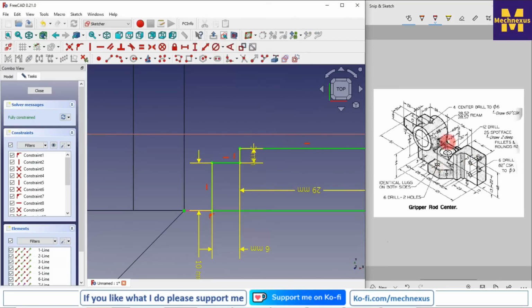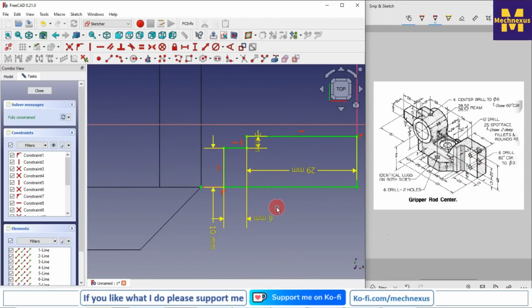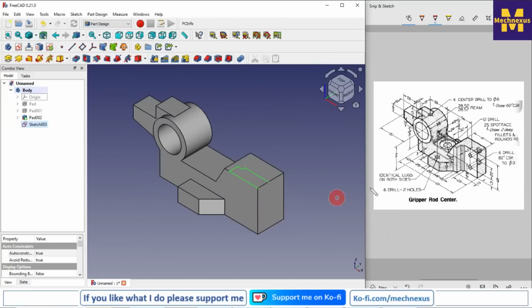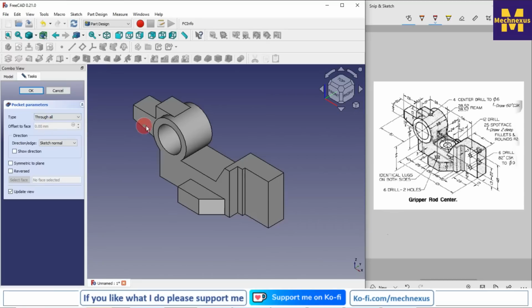So you can check all these dimensions here. If you read the drawing, you can find these dimensions. So we have the profile here, and now I will close my sketch, switch to the flat lines, and now we will completely remove the material from top to bottom. So click on the pocket tool, click on through all, and say OK.